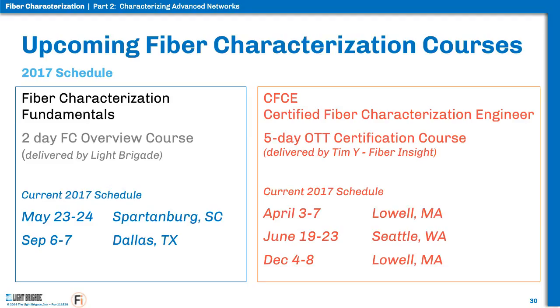And I believe this question has to do with environmental things, and when to get the worst case measurements. I'm thinking that may be caused by temperature variations due to weather conditions. Well, again, we're talking PMD here. So again, if you just take a PMD shot one time, it's the PMD value at that moment in time. So if you were to turn around and make that measurement a few seconds later, let's say I even flipped my test cord over 180 degrees on the table, I'll get a little bit different measurement.